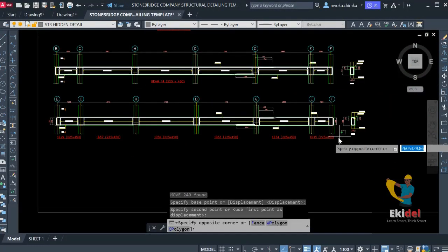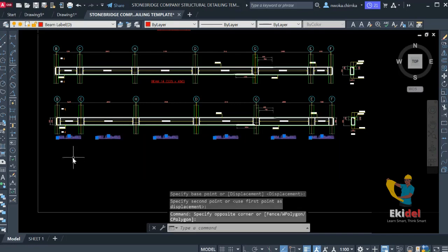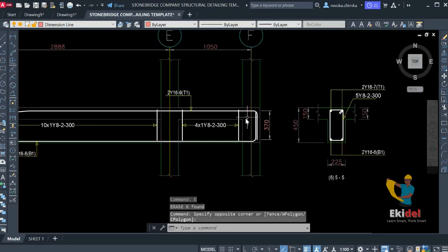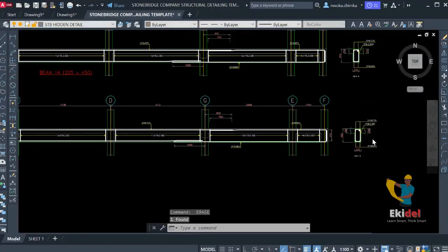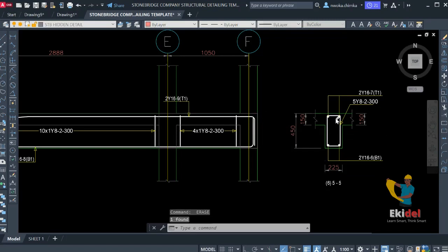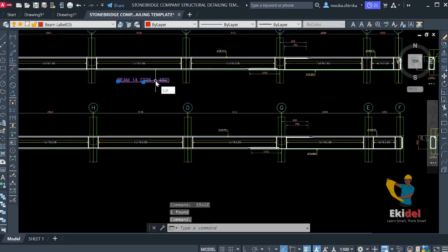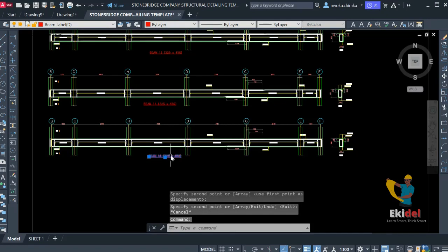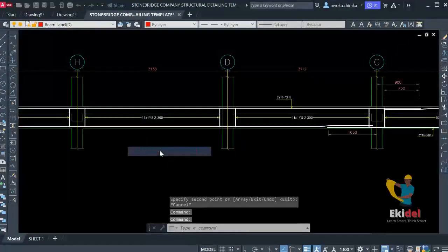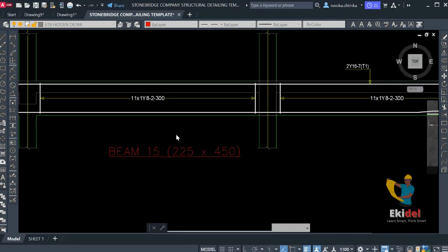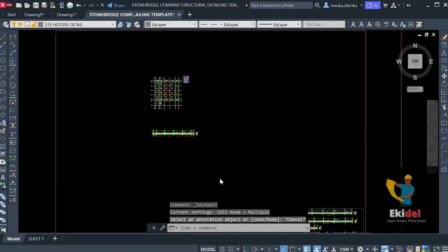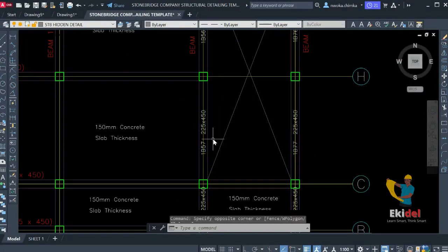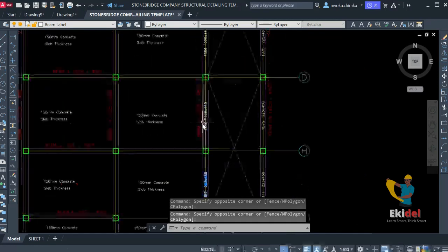So remove this unnecessary beam naming that came with it, because we have already identified that. So we can now remove it, and we remove this also, and remove this also, and then just take this off. This is always double sometimes, and then copy this and change this beam naming, which we have already identified as beam 15. So we just go here right now and put this place as being 15, and then we now go to the layout and remove the unnecessary one that came with this layout, which is this, because we have already changed the name to a master name, which is 15.